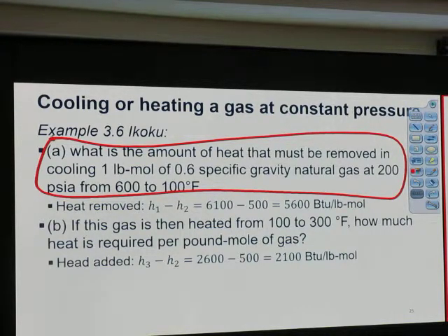How big is the radiator you need? We don't know until we get that number. I don't tell you how to design it. I don't know it myself, but the guy who buys this will need to know how many turns and how many fins we need. They need that number. How many BTU do you want to remove? So what is the cooling capacity we need?